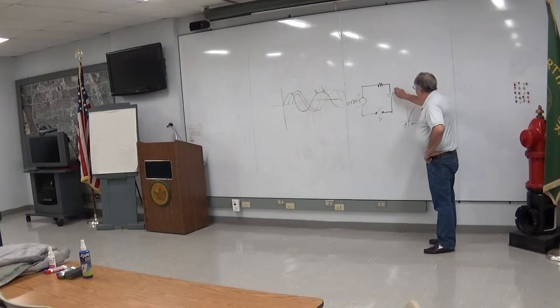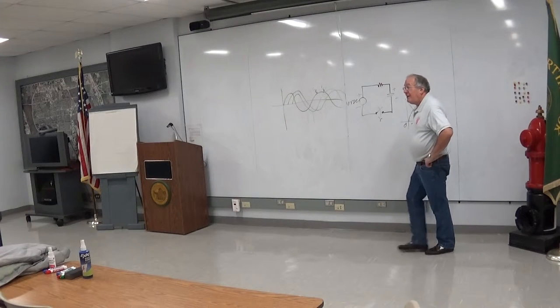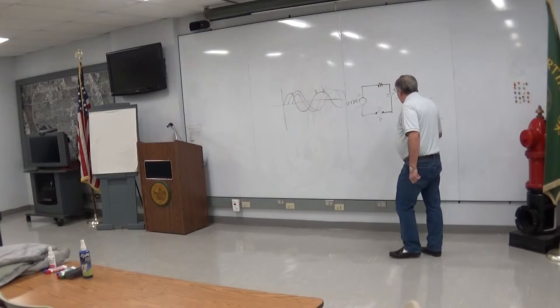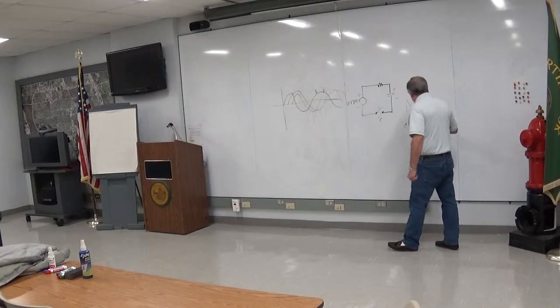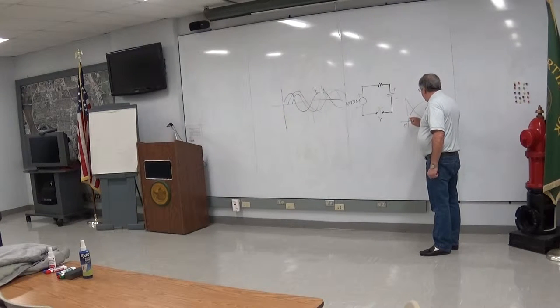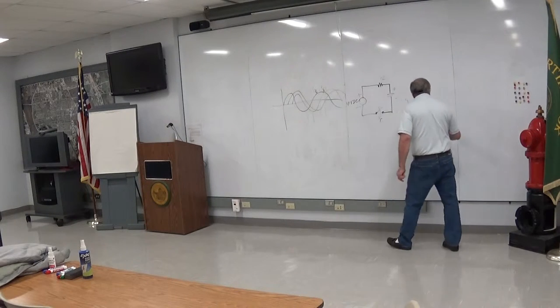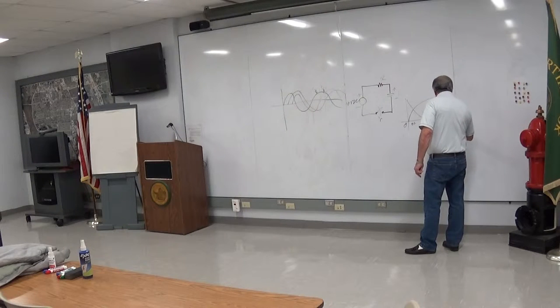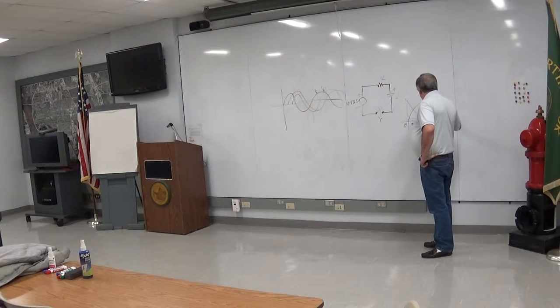The voltage on this thing will build, and the current through it will start out immensely high and then drop to nothing. It won't go below 0. But you're going to have a process where there's a time lag, and we also discussed the fact that this time tau, which is equal to this resistance R times this capacitance C, is going to represent where this will sink to 37% of the starting point.